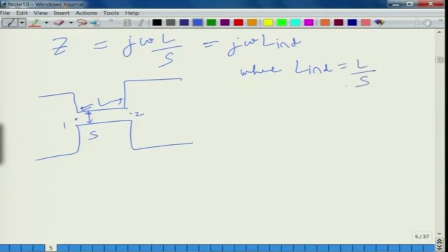so this is clearly the effect of sandwiching a small tube of a very short length L, whose cross dimensions or diameter is much smaller than the two flanking cavities. Such a constriction acts like an inertance at low frequencies. Its basic effect is to act like an inertance, and we will see why it is important when we discuss things like the Helmholtz resonator. So far we have seen quarter wave resonators, but we will soon see the Helmholtz resonator also.